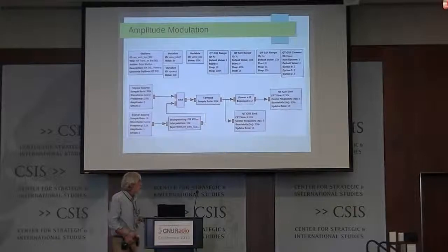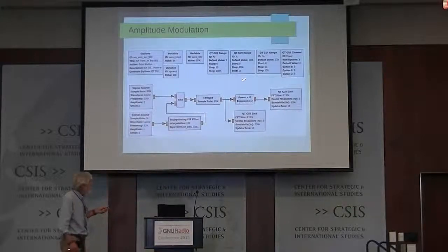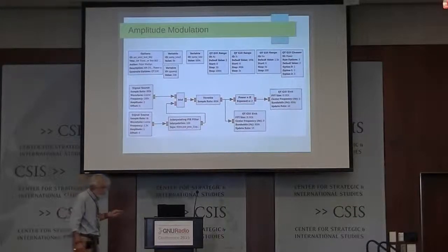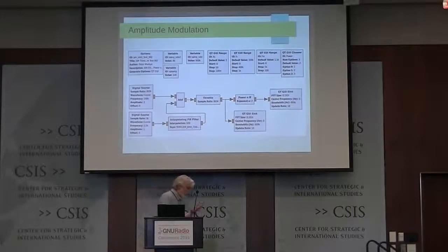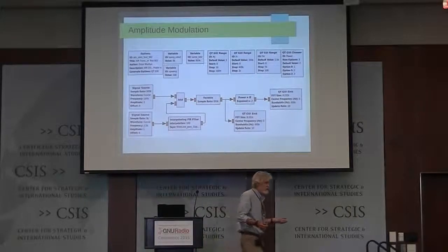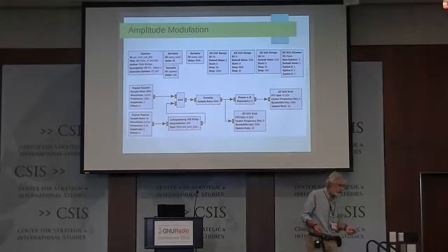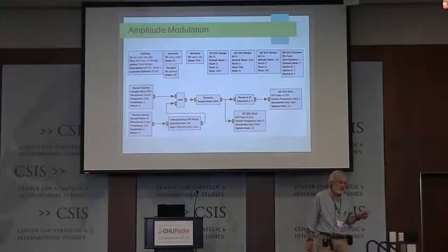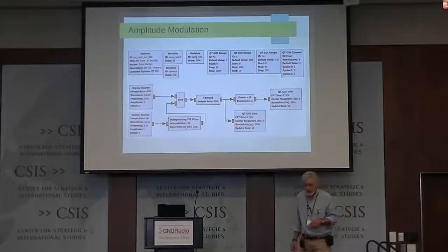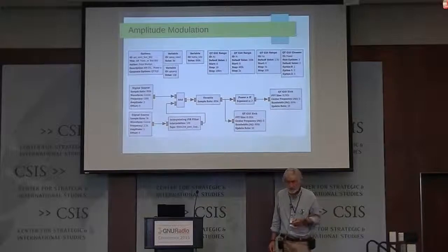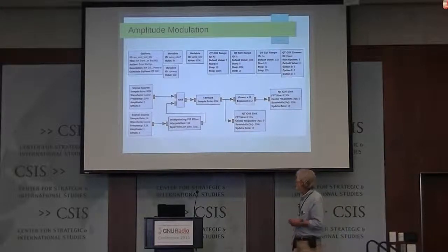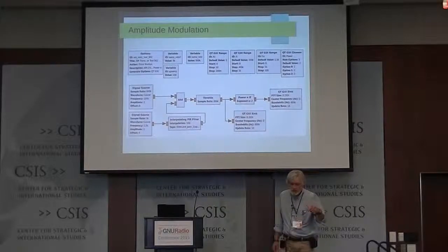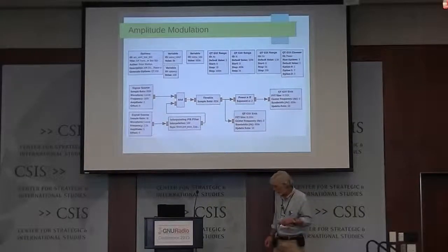The second version uses the power n, with an exponent of n equal to 2 or n equal to 3. If you do n equal to 2, you get the AM suppressed carrier signal at twice the frequency of the carrier. With n equal to 3, you get it at the actual frequency of the carrier.